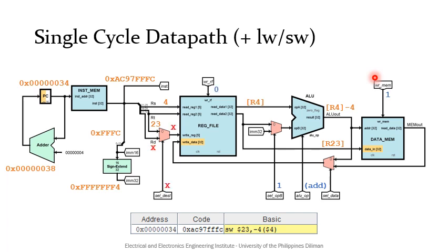Note that we are not writing into the register file, so the write RF signal must be deasserted, and with that, the write reg value is a don't care. Similarly, whatever is being fetched from the data memory at this specified address is a don't care, as well as whatever is being fed as the write data input to the reg file, since again write RF is deasserted.